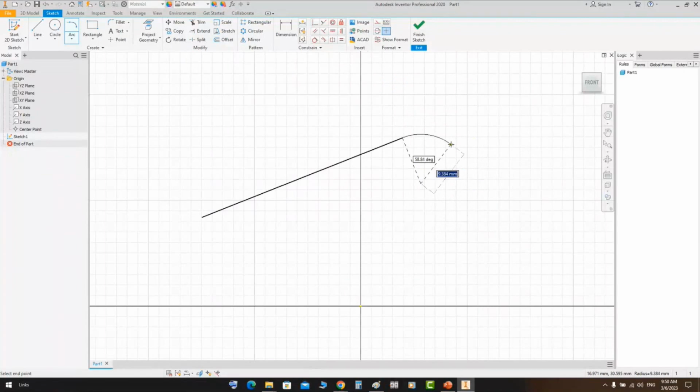By the way, you can define the angle and the radius of this arc automatically during selection, and press tab to move to the second text box. Now, if you click enter, you will have this arc. We defined the arc angle as 60 degrees and the arc radius as 10 millimeters. So if you select the arc again, you can make arcs tangent to each other like that from the end. Okay, during entering, you can define the dimension of this.